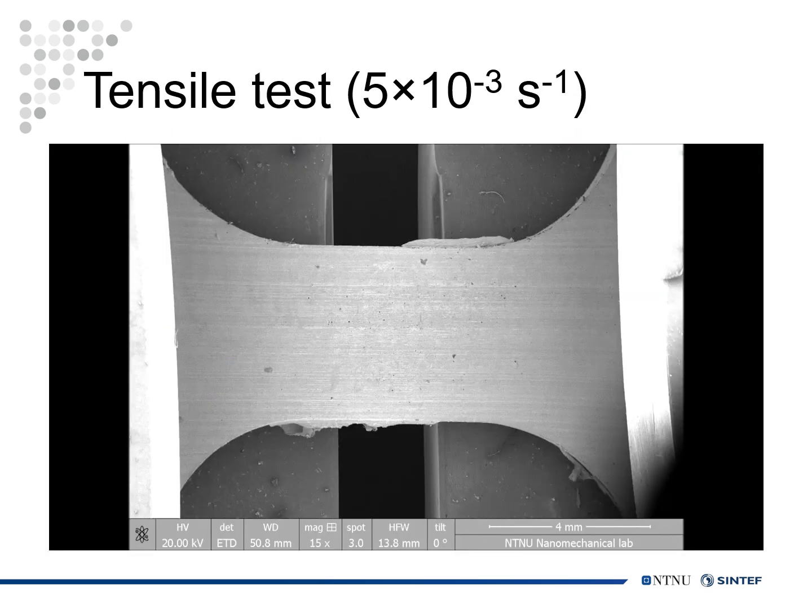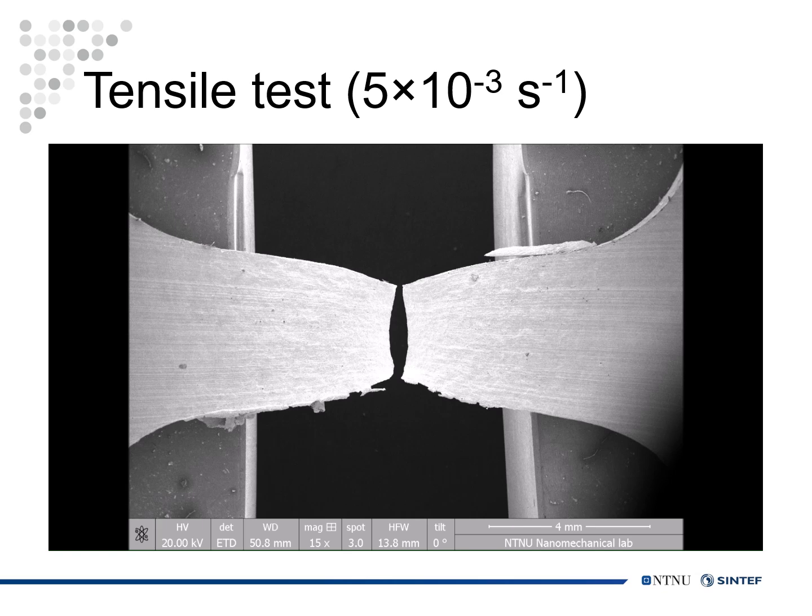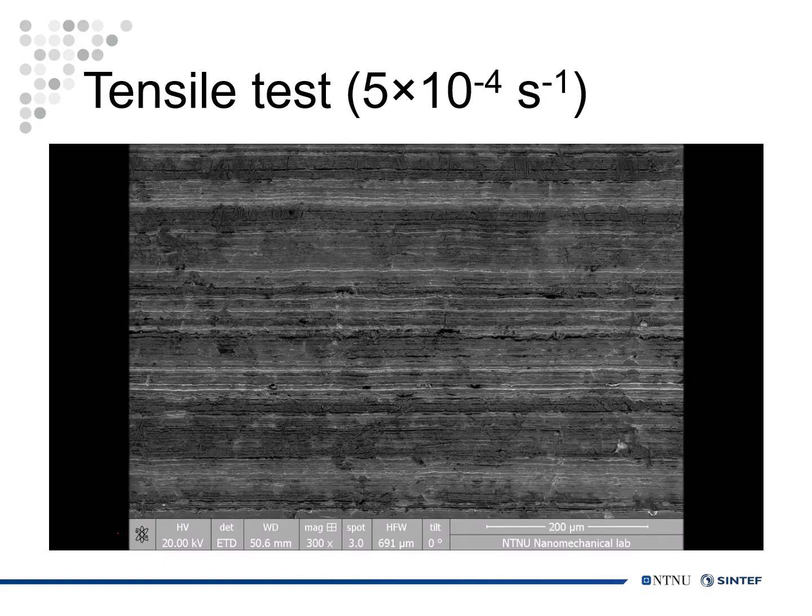First, let's see an overview of the monotonic tensile deformation behavior. The specimen was directly loaded to necking followed by final fracture. The fracture was ductile without any unexpected brittle behavior. However, this magnification is not capable of observing local deformation behavior. So let's try with a higher magnification.